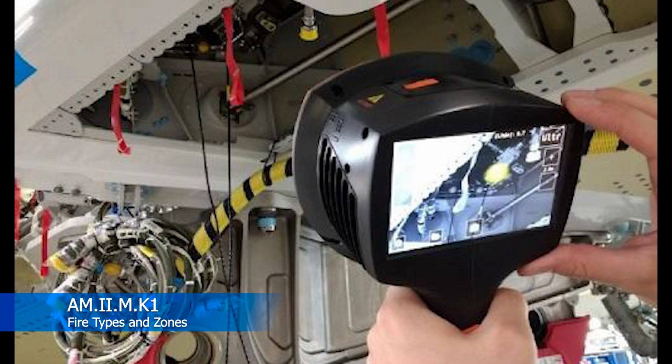So if you have a bleed air leak somewhere on that airplane, there's a good chance that it could cause a fire. In the picture here, the guy's demonstrating trying to find a bleed air leak with an ultrasonic imager. We're going to teach you how to do that. But just know that you need to be really careful working with bleed air, because if you were to crack a line or cause a problem, it could potentially lead to a catastrophic event.